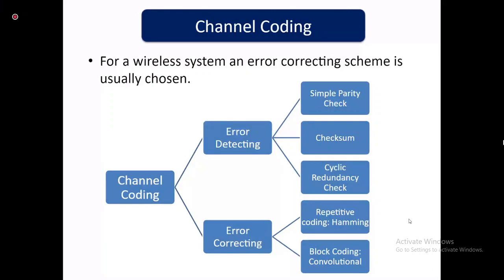So if I say the convolutional coder's rate is 1 by 2, that means that I have X amount of data bits that I want to send out, but because of convolutional coding, I'm actually sending out Y amount of data signals. There might be shorter packets or scenarios where your wireless data is not always completely corrupted. There is only a chance, maybe a 1 in 10 chance, where your data might be corrupted. In those cases, what we do is we do something called a retransmission architecture, where we send from the transmitter, we do an